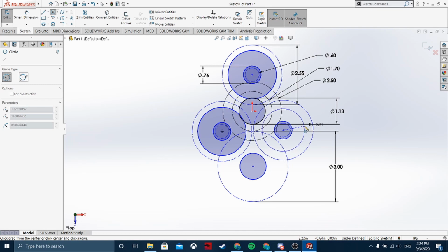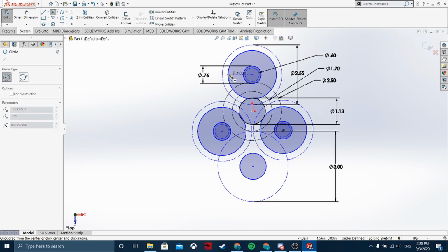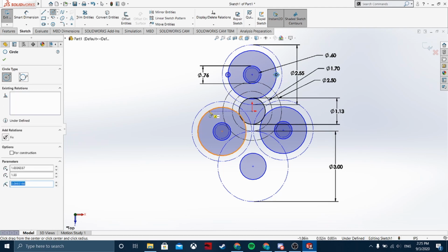These circles on the Neo motors have built-in screw holes so that you can attach those motors to stuff, right? So we have to create screw holes, or holes to actually put bolts through those screw holes. So I'm going to create 2 screw holes for each Neo motor, right?